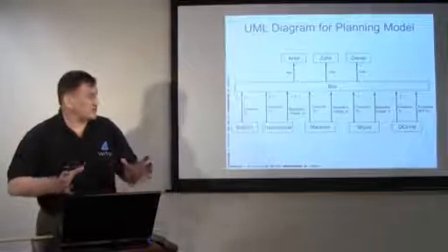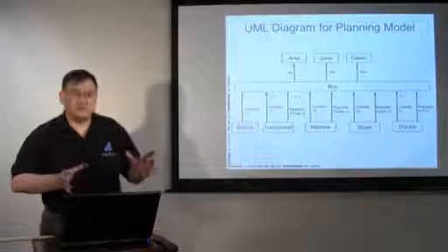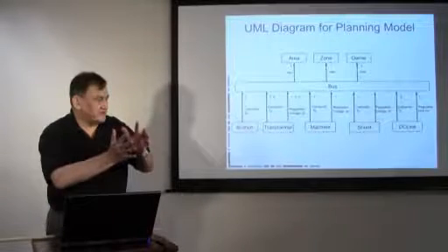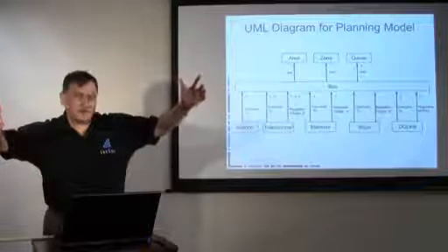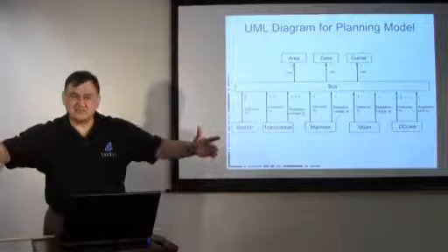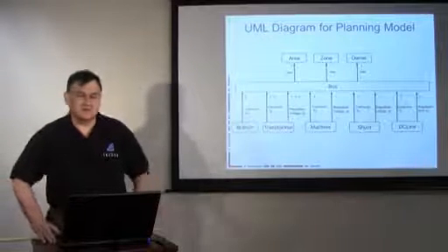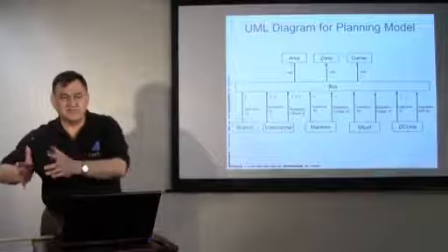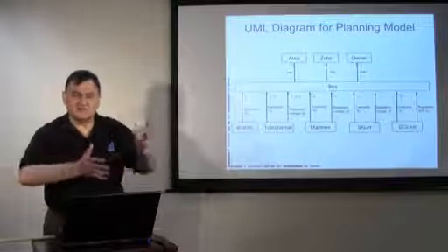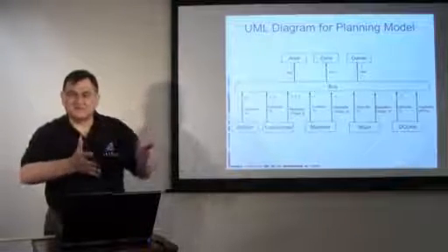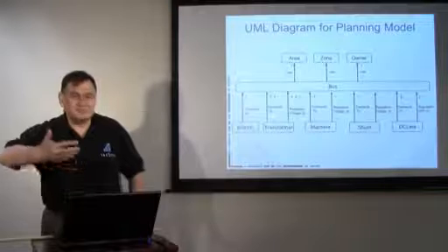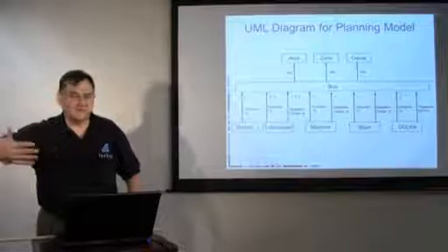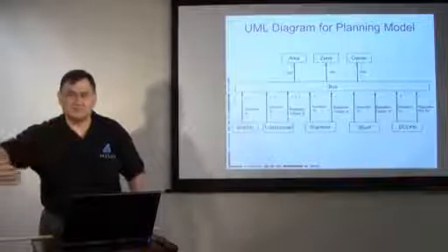The planning engineers would allocate a certain region of the country. So literally, they'd decide to say, we can allow 100,000 buses for the eastern interconnection, and everything in the southern area is going to be buses 10,000 to 20,000. Everything in the Midwest is going to be 20,000 to 50,000. And they would deal with bus numbers. And to operators, those bus numbers made no sense at all.